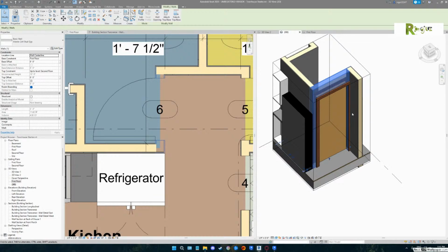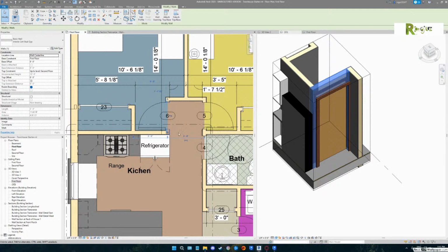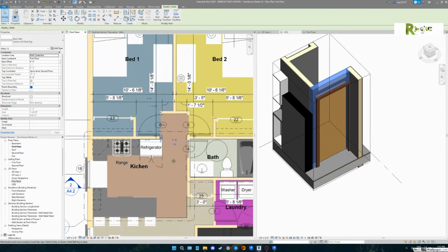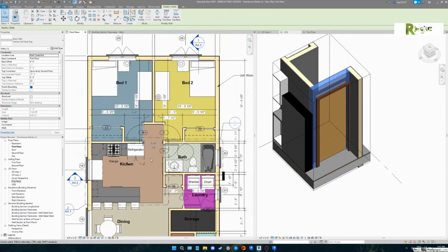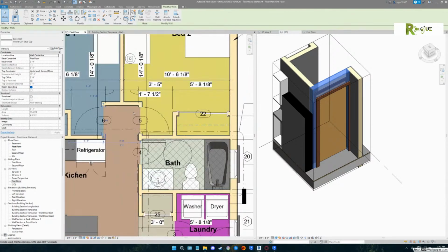In your plan view, zoom out just a little bit. See, you did good at dimensioning the vertical walls in that view, but you didn't do good at dimensioning the horizontal walls. You did tell them where the one closet wall is. Zoom out a little bit more. Yep, you told both closets, but you didn't tell them where that end wall is. You see which wall you have it dimensioned? Oh, I see. Yeah, this one right here. For this wall, no, I didn't put it out there.